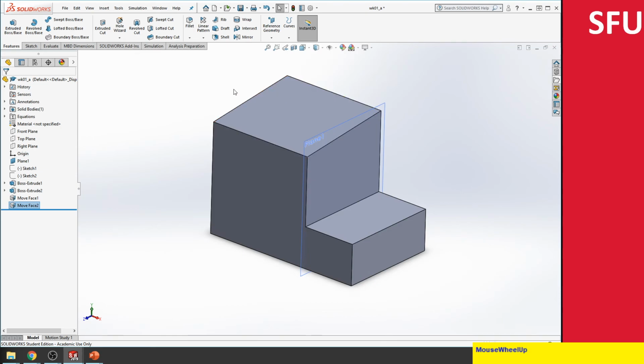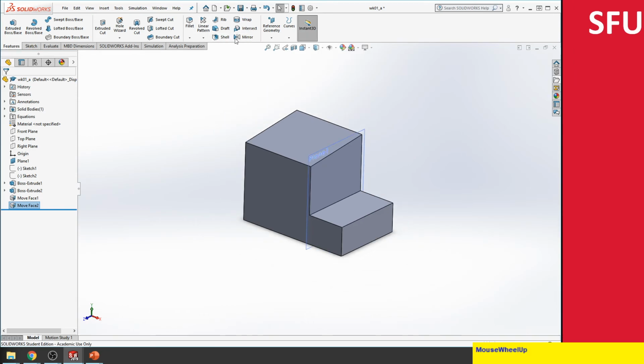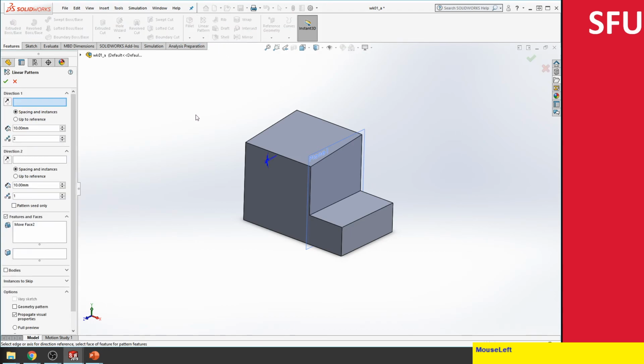Then we are going to look at the pattern. Notice now we are in the feature mode. We have the pattern in the sketches, but you can do the pattern in 3D as well. You can do a linear pattern or a circular pattern, and then you can mirror, and do curve driven patterns and sketch driven patterns. You can take a look at this and see how it looks, but we'll do the simple linear pattern for now.